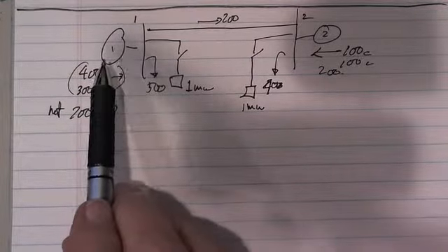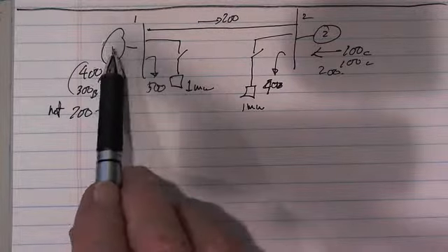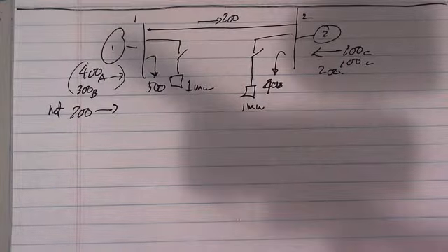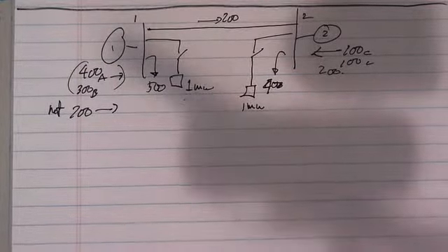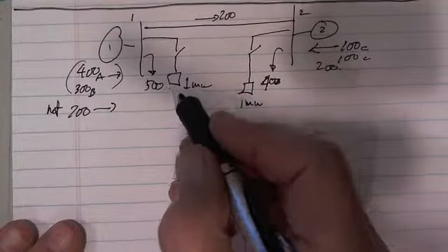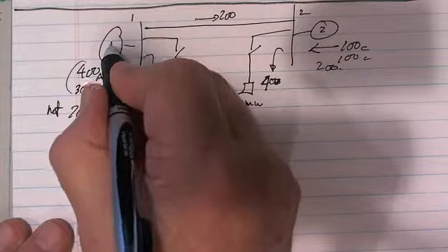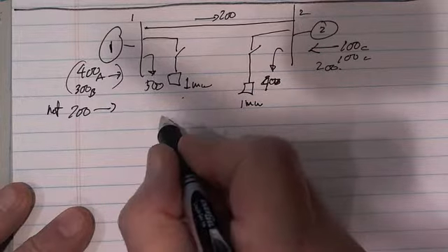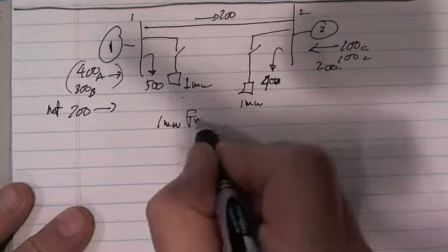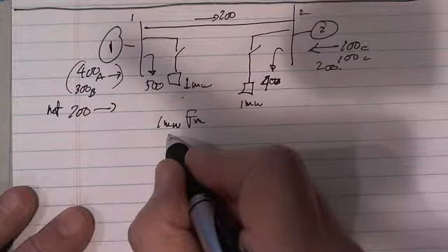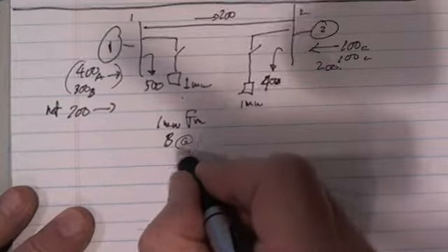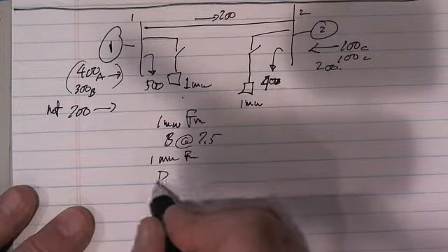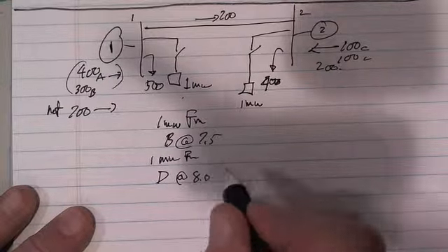So this guy is supplying 700 of the total. This guy's supplying only 200. 200 is flowing across here. If I want to add 1 megawatt, it's pretty obvious here. I'm going to buy it from here, because, well, at this point I could get 1 megawatt from B at 7.5, or I could get 1 megawatt from D. Remember my high price one here at 8.0. Well, I'm going to buy this one.